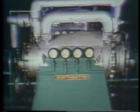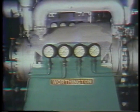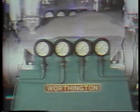Now, situations in the plant where energy is used follow these same laws. Knowing that a specific situation requires a specific amount of energy will help you determine if something is wrong. For example, an electric pump draws a certain amount of current to operate. If the pumping conditions remain constant, but the current drawn by the pump increases, indicating the pump is using more energy, you know that something has affected the energy conversion in the motor or pump. Now, this could signal a problem, and it should be investigated.